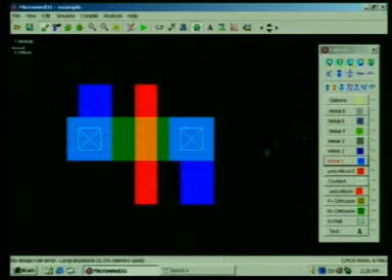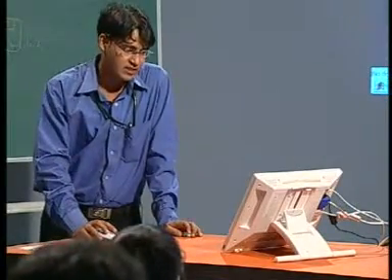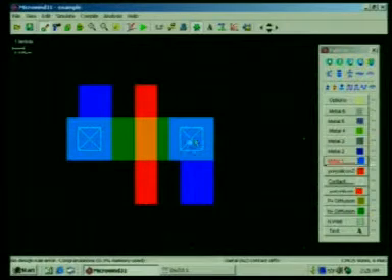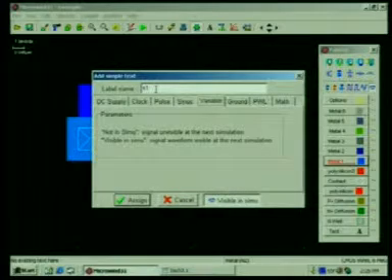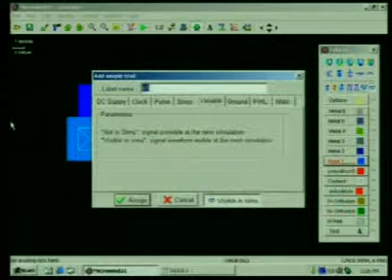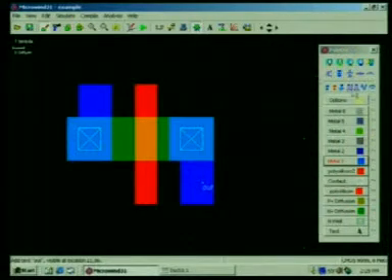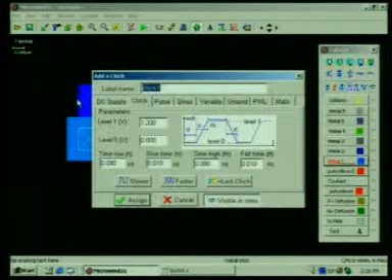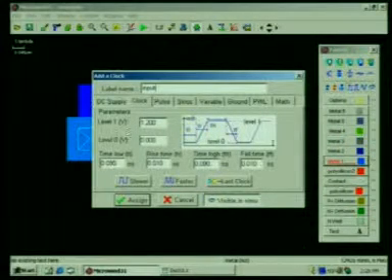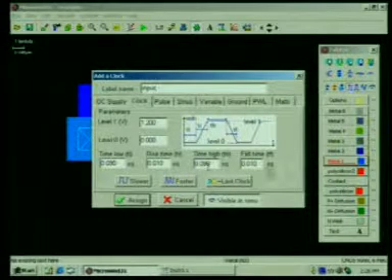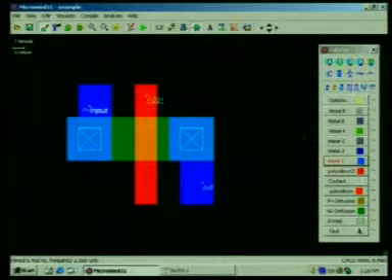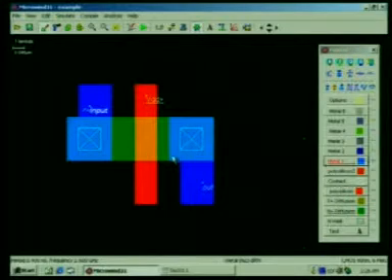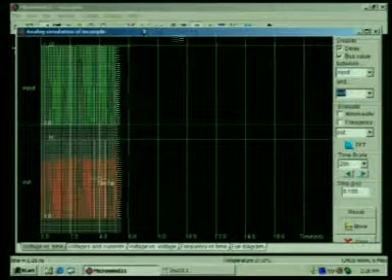After that, now I want to verify whether it will work as a switch or not. So I need to put some signal here, and I need to close this one gate, and I need to put some visible node to see the output. So I will click this, this is the visible node, put it here, just name that, assign. Take one input signal, and you can vary the frequency also, even rise time, fall time, high time, you can vary this one, just assign. After that, just apply VDD here, so that it will be closed every time. Now go for simulation. Actually after this layout, I will go for simulation.